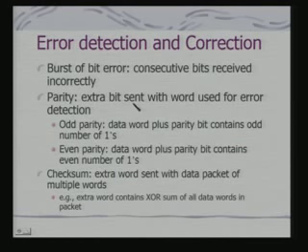An extra bit is sent with the word, used for error detection. If there is an isolated error, we can detect it. If there is always an even number of errors, it gets masked, and I cannot detect that error if I am using parity. It can be an odd parity or an even parity. In fact, this is a basic error detection scheme which is part of any of these asynchronous protocols, even as simple as the RS-232C protocol.